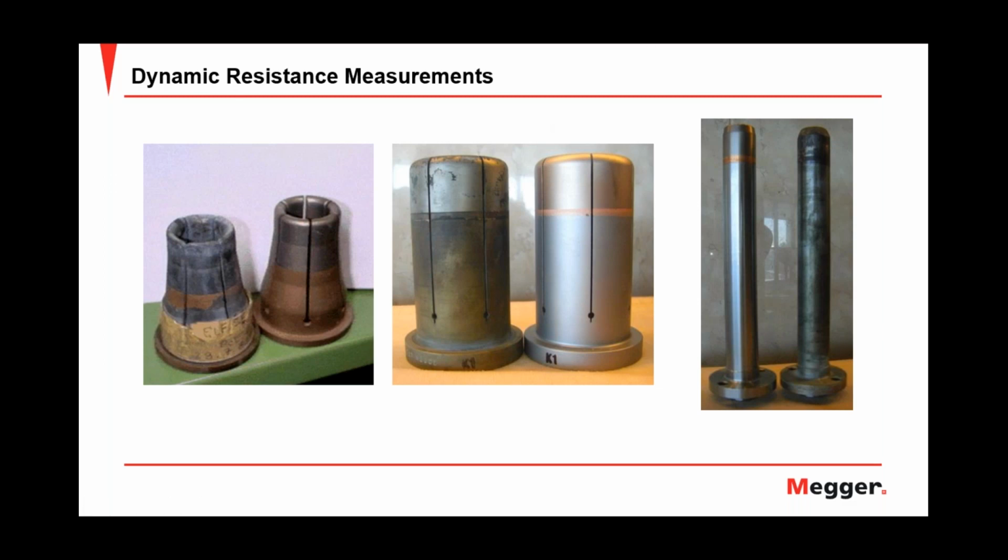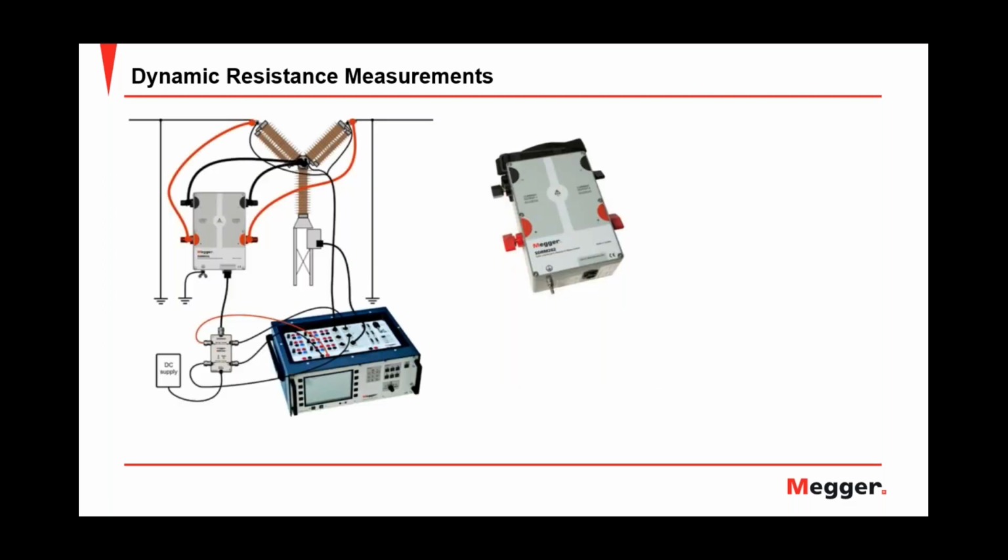Okay, so as I mentioned, instruments capable to perform this type of measurement are both Eagle and TM series, 1700, 1800s. Some accessories are needed as an extra. As I said, you need to inject current across the main contacts of the circuit breaker during the operation. And that is done with what we call an SDRM supply, which can provide up to 200 amps on 2 channels from a single box.